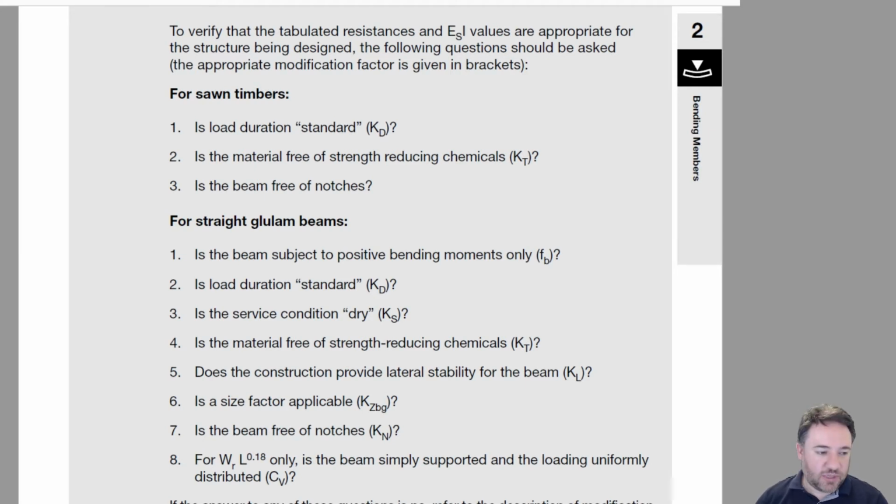It just means that you have to be a bit careful about how you select your values. So for straight glulam beams, which is what we're designing, is the beam subject to positive bending moments only? Check. Load duration is standard? Check. Surface conditions dry? Yes. We don't have any KT, that's check.